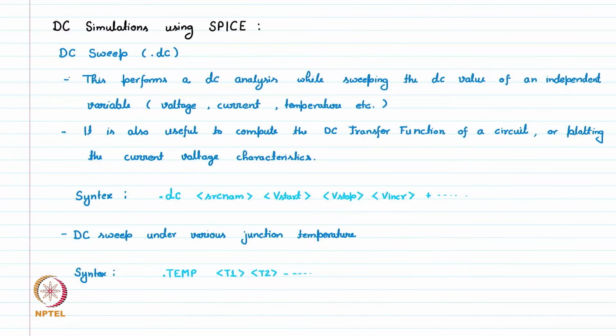So, the same statement we can use because temperature is a parameter which we choose very often. So, there is a separate command itself for DC sweep of temperature, .temp, and this is equivalent to,